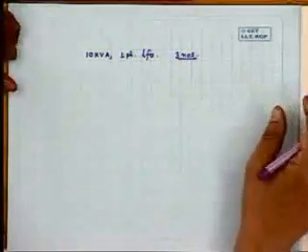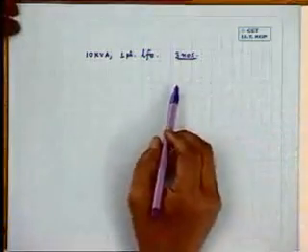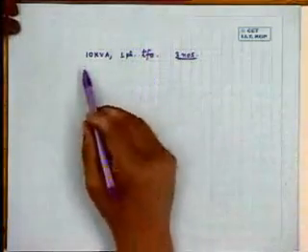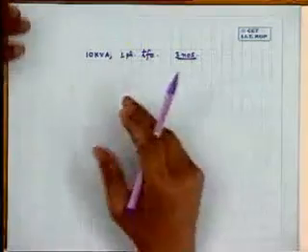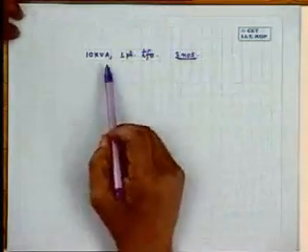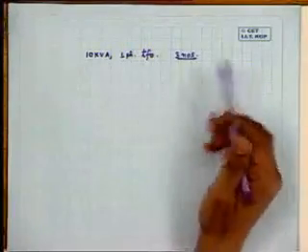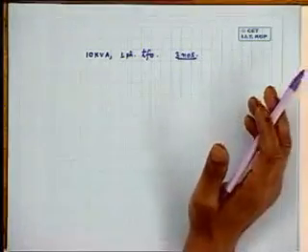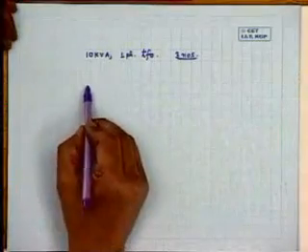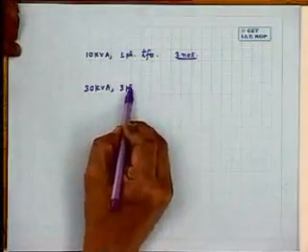You can get 30 kVA output from this for balanced loading. So, to cater a load of 30 kVA, there are now two options before me. One is you can have three 10 kVA transformers and supply that 30 kVA load, or you can have a 30 kVA three-phase transformer.